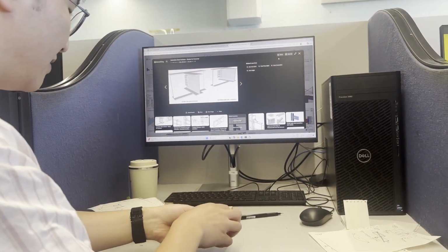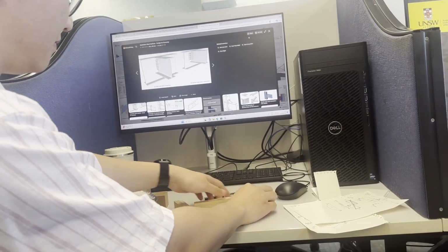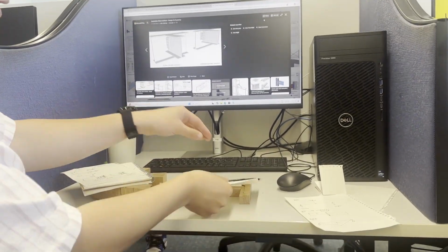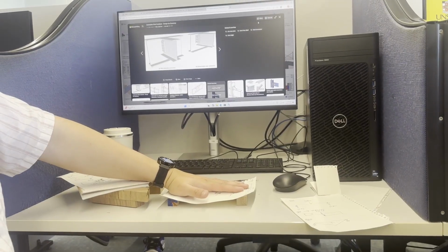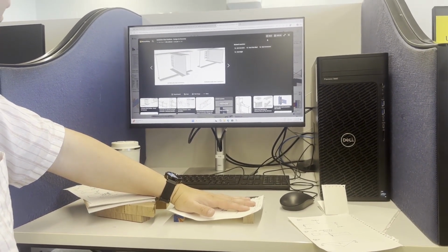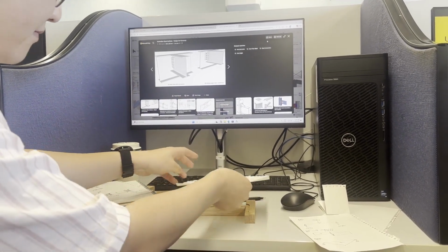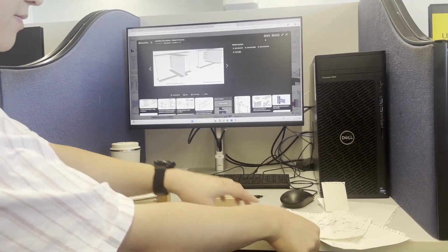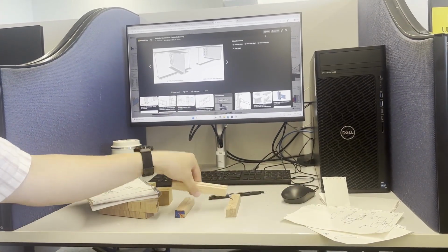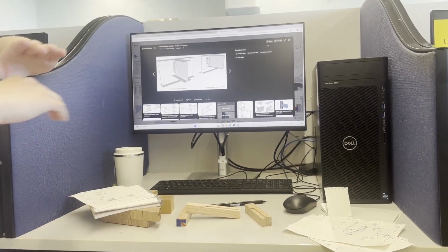Yeah, it comes down to the fact that, remember, you want everything on the top surface to be even, so that when you put something on top, like a load or a roof sheeting or a concrete slab, they're taking the loads all at once. Because if there's a gap, like that, and there's a concrete slab here, you know. Does that make sense? Yeah. So you cope it just so that the top plane is flat. Yeah. Yep.